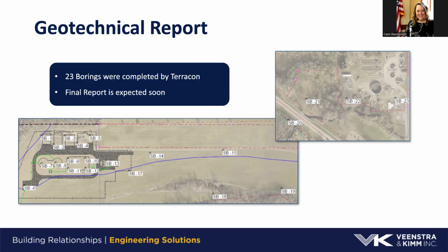They did not encounter any bedrock. In a couple places we had them go down to 80 feet. Solon seems to have some pretty variable conditions with regard to bedrock. We had kind of wanted to verify there wasn't any on site. They did not find any. All the borings went down, I believe, or most of them went down to 30 feet at least below grade, never found any there. And we did a couple really deep ones to 80 feet, still nothing.